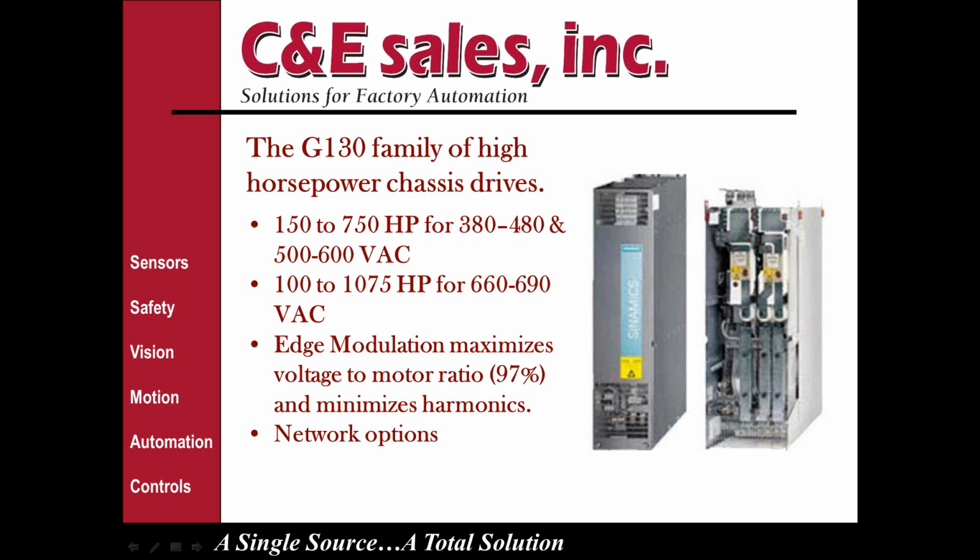Past technologies, you had a trade-off. Either you had a high voltage level and high harmonics, or you were able to minimize harmonics, but you lost some of the voltage coming in line, typically 90 to 93%. So with the new edge modulation that is a Siemens feature, we can get a much higher ratio of incoming voltage to the motor voltage, which gives you much more efficiency, and yet we still minimize the harmonics going out onto the line. The G130 has the full range of network options we've talked about before.